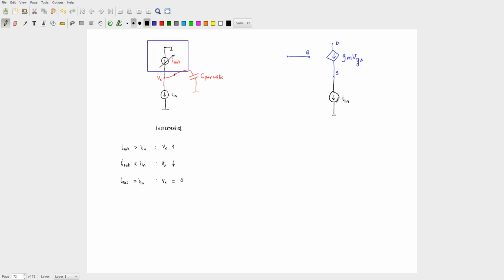It's done its job. What is going to be Vs when I out is equal to I in? To complete the circuit, I have to put that, and then my I out is essentially the current flowing through there. So you have I out and I in. When I out is equal to I in, what is the value of Vx, which is now Vs? 0.